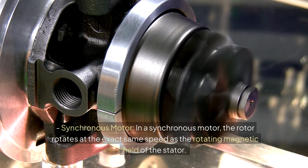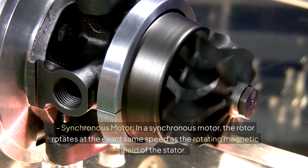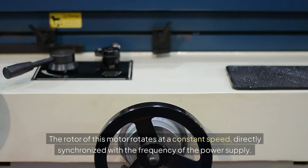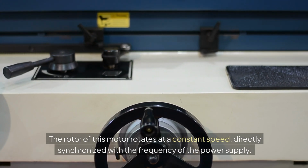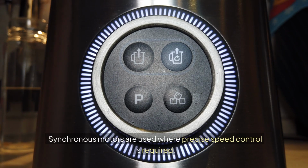Synchronous motor. In a synchronous motor, the rotor rotates at the exact same speed as the rotating magnetic field of the stator. The rotor of this motor rotates at a constant speed, directly synchronized with the frequency of the power supply. Synchronous motors are used where precise speed control is required.